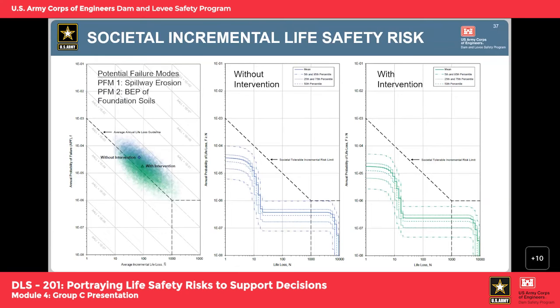Yeah, I guess it kind of depends on how you define significant. So pool 610 has the highest incremental consequences at 16, but the top of dam has incremental consequences day and night of 4 and 3. So it's not 0, but the top of dam is slightly lower than 610, and that was due to the larger non-breach life loss at that pool.